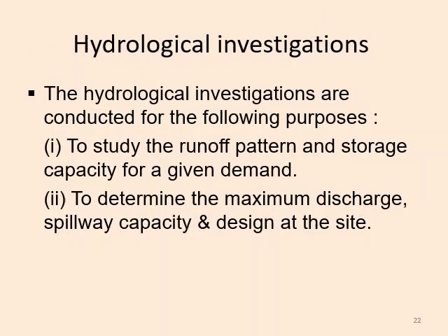Next is hydrological investigations. From the hydrological investigations, we will know the runoff pattern and the storage capacity for a given demand. Runoff pattern means how much water will flow over the land surface if rainfall happens on a particular area.